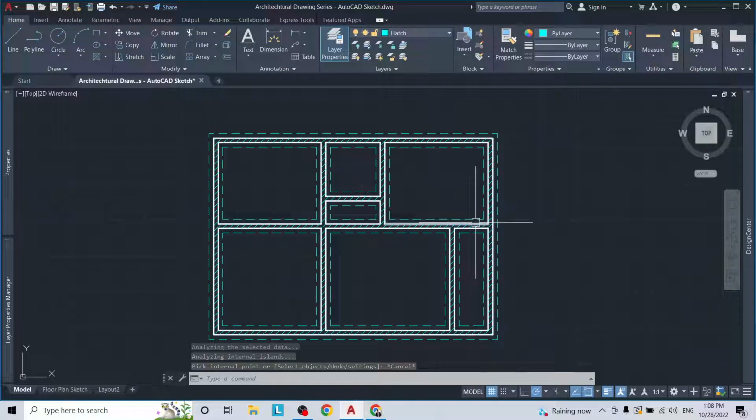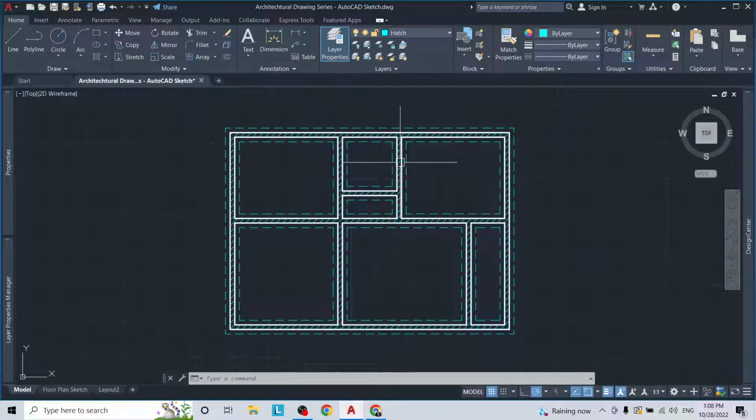So that's the hatch in. Now it's just dimensioning left to do. Now there are multiple ways to dimension your foundation, but just keep this principle in mind. You want to show enough measurements and details in your dimension so that whoever is building this house is going to know exactly where they are going to dig the trenches to put these footings and foundation walls.